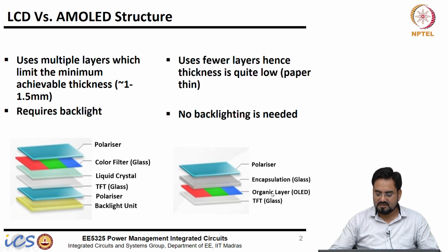This is your LED, but here I have shown 3 different color LEDs. It is quite possible that you can have all 3 white LEDs, and on top of that you put a color filter. So the cheaper AMOLED, these OLED displays are made using color filters and white LEDs instead of color LEDs, because that is more expensive. Another thing is that different color LEDs require different drive voltages, because their forward voltage is different. So it becomes quite complicated to drive those.